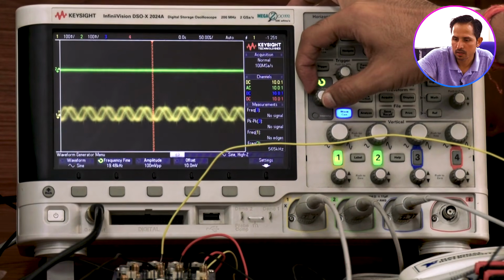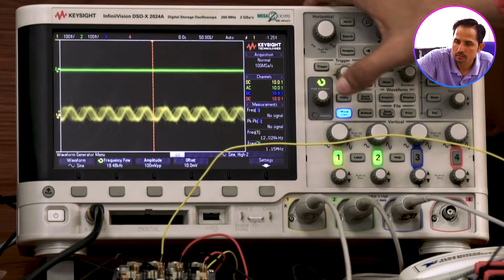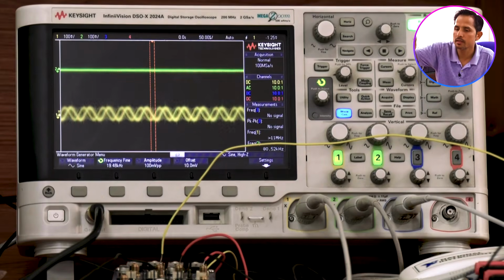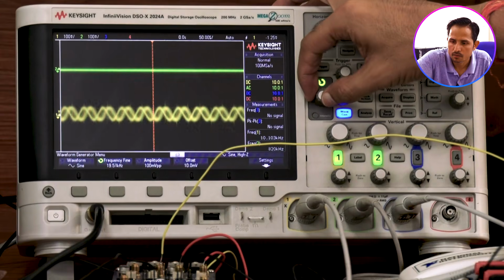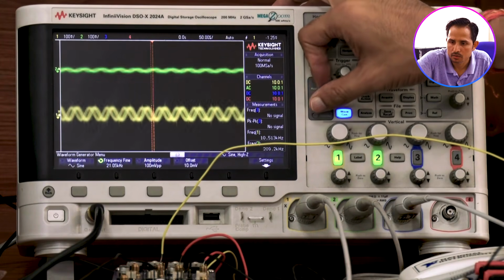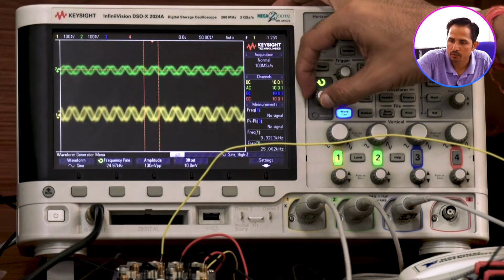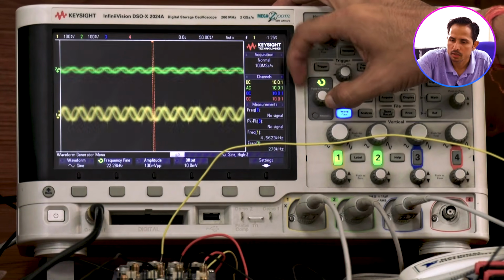We can see that for the signal which I am giving with the DC, the program is able to extract the DC component basically and remove the overall AC signal. The green signal is giving me a DC component only. If I increase the frequency, it will pass these signals, but on this particular frequency, 19.53, it should give me the DC component only.